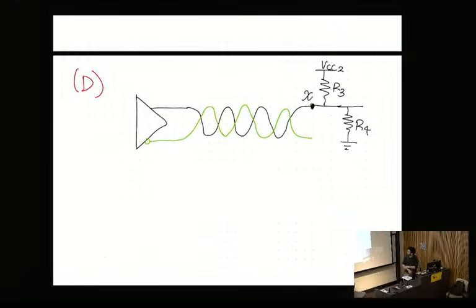Okay. Generally with transmission lines, why do reflections occur, just generally speaking? Mismatching impedance. Is this a problem at low frequencies? No, because at low frequencies the wavelength is very long, like kilometers long. It means we don't really see it as a wavelength.